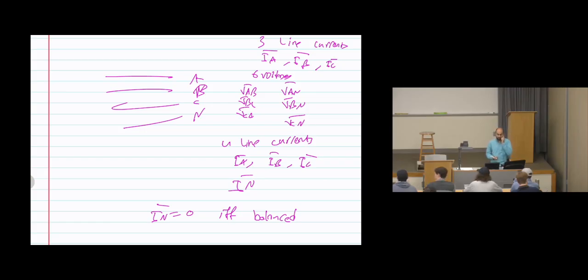And I mentioned as well, 3 wires are most likely used on high voltages, extra high voltages, when we transmit power over very long distances, where I can guarantee the system is balanced and make sure there is no connection in the middle. So if I'm transmitting power for 100 miles, 200 miles, whatever, there will be no unbalanced situation. During transmission, to get a cheaper cost, it's better to have 3 conductors, while in distribution, you need 4 wires.